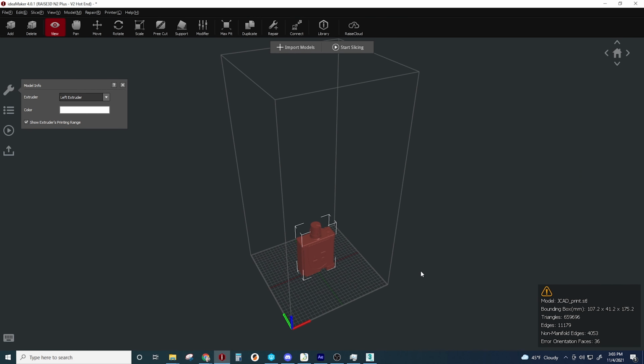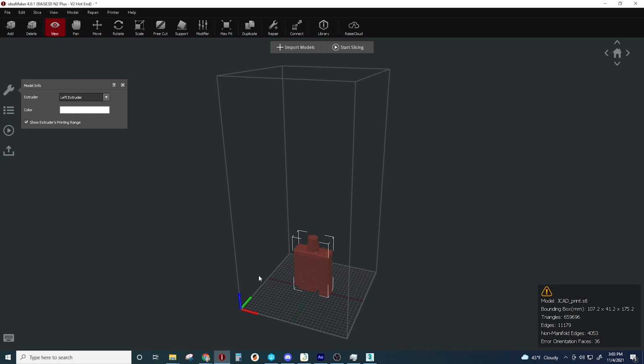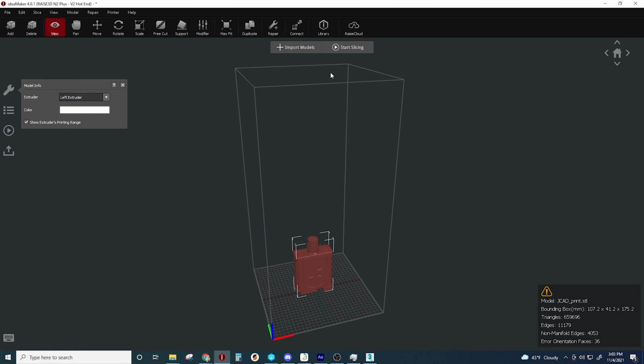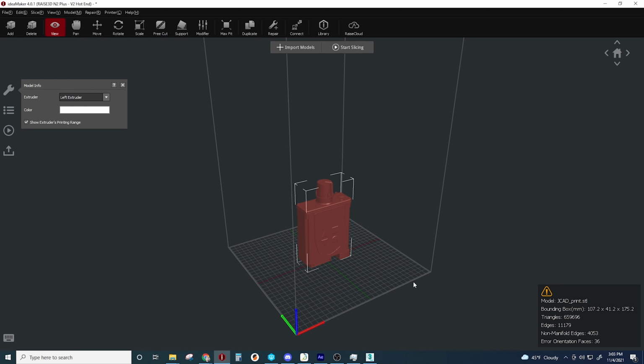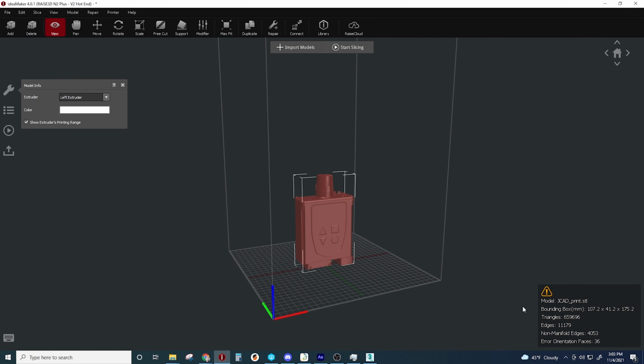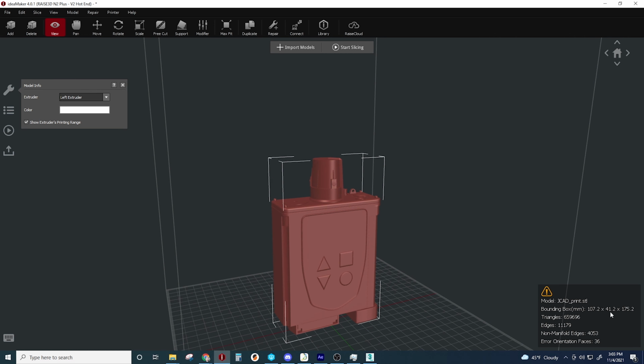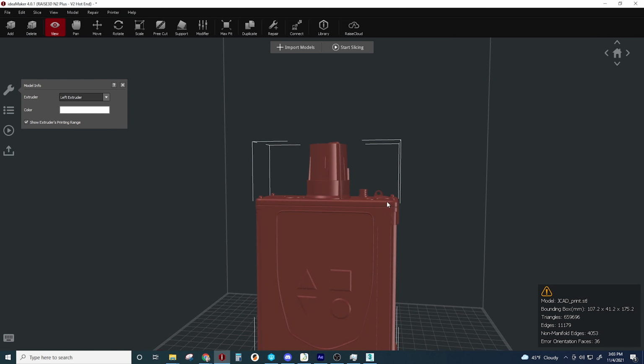And you can see here, this is a pretty large print volume for the printer. It's called a Raise3D N2 Pro Plus, and we have a 12 by 12 inch build volume that is 24 inches tall. So my object fits just fine within that build volume, and I can just double check the bounding box size here in millimeters. And then I could just plug these numbers into Google and verify that this is the right scale according to the scale in 3ds Max. And I can tell just by looking at this that it is.